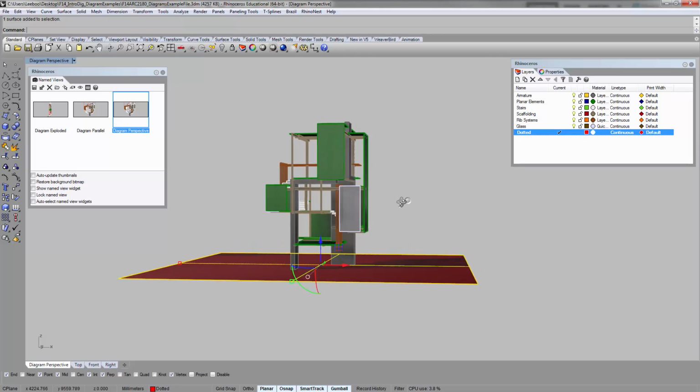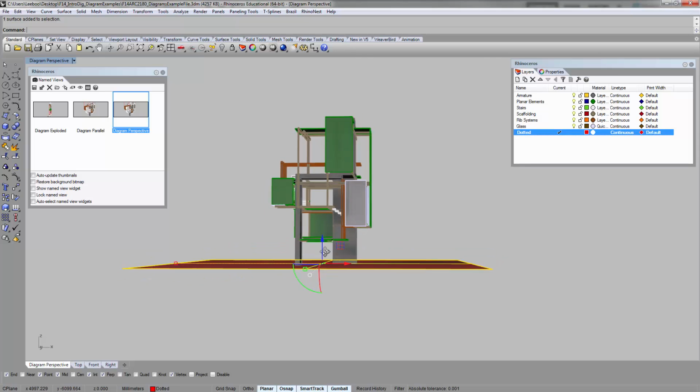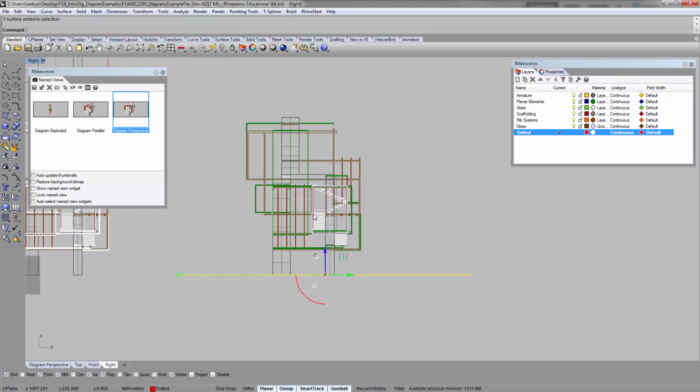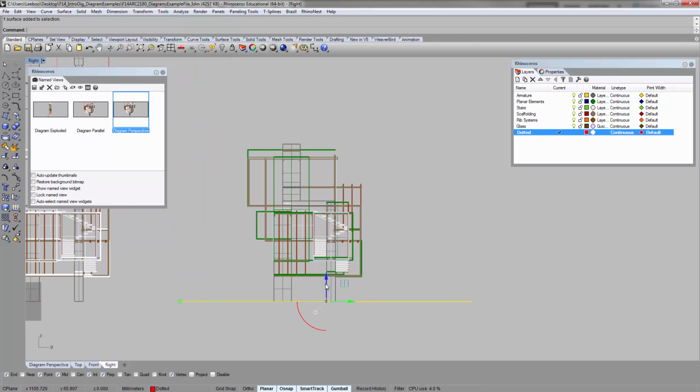And what I'm going to do is, you can do this in the 3D view. I tend not to switch around views a lot. I'm just used to using the 3D view. But if you're getting confused, you can come to one of the side views, right? Select the plane that you made and use the Alt key to Alt drag and copy.